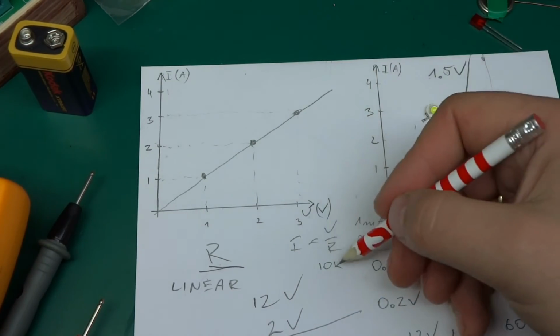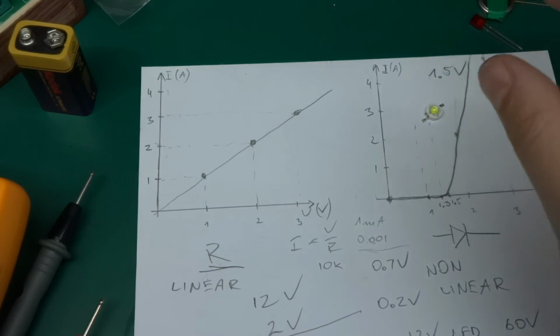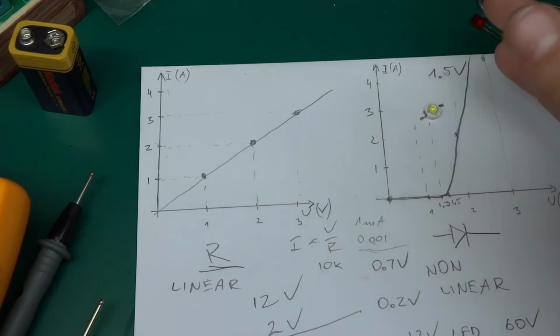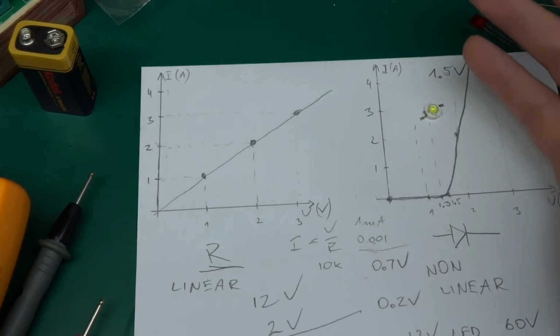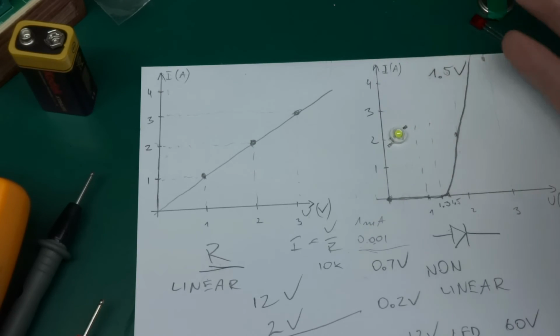And anything between 1K and 10K in this matter would do it, and the LED will just light up very, very dimly, because you want to do between 1 and 10 milliamps. Shouldn't damage any LED. Actually, it would work just fine.